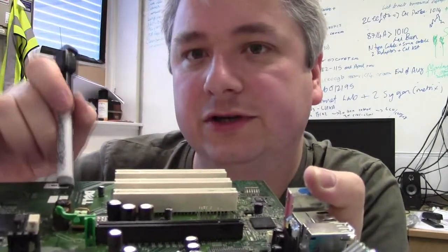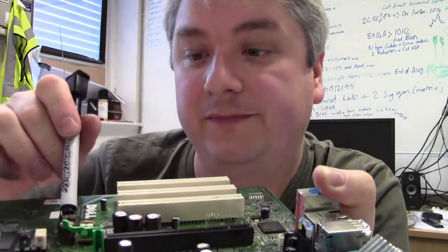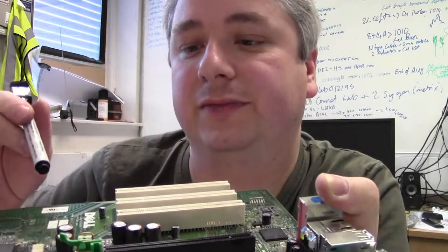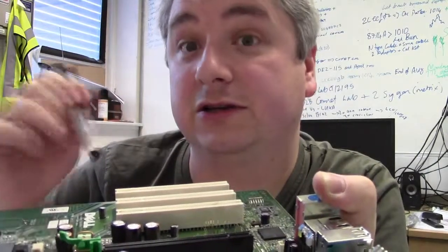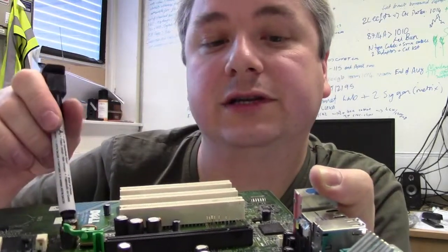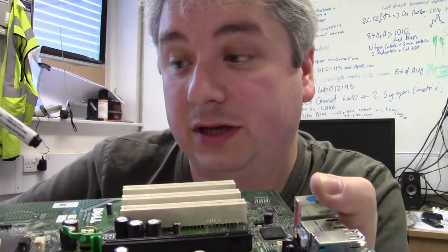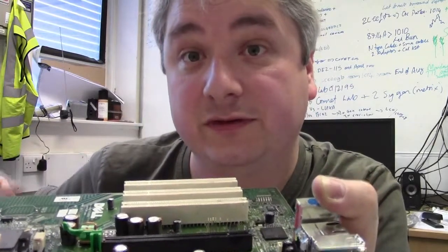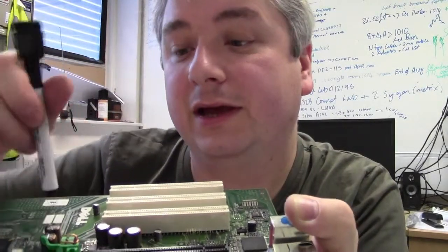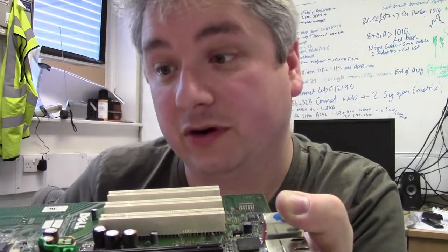But you'll get them in all different sizes and all different types. Now these are electrolytics, and you generally only ever get that value in electrolytics. You'll probably find some super caps about that size as well, but they're electrolytics, and the only way to pick it out is by working through, similar to what you did with your designing, except you're working backwards in this case. You know what the value is and you know what the dimensions are, so you measure the dimensions, and you can go off and buy the right one.